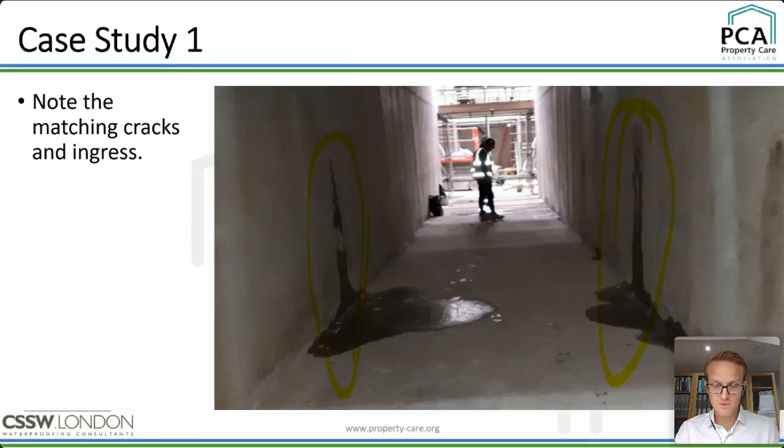And we did some work with the concrete contractor, saying, well, it was the main contractor who did the rebar design, which determines your crack width, and the concrete contractor simply put the mix together and poured it. Really, it's not fair to put that all on the concrete contractor. So you can't say whack a waterproofing additive in and that's watertight concrete. It's more complex than that. You have to consider your crack width calculations as well.